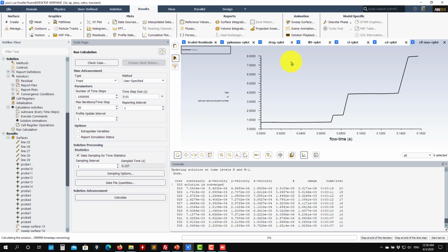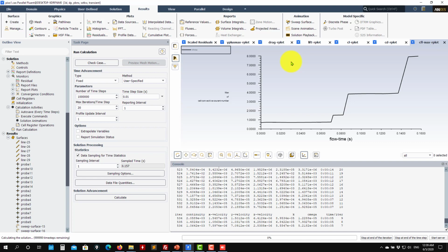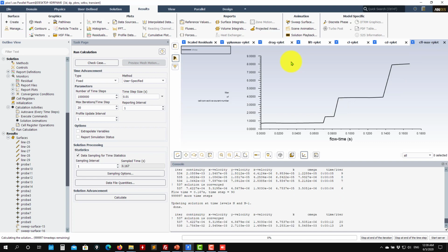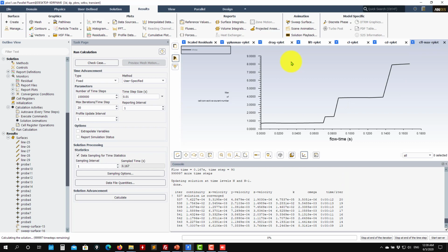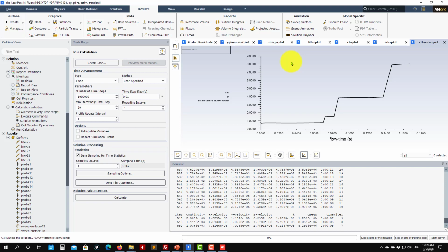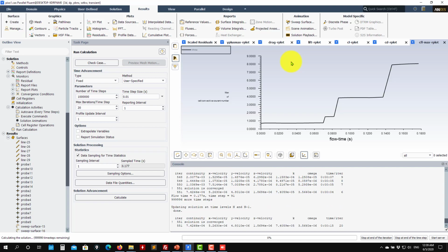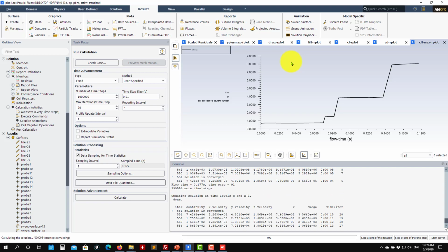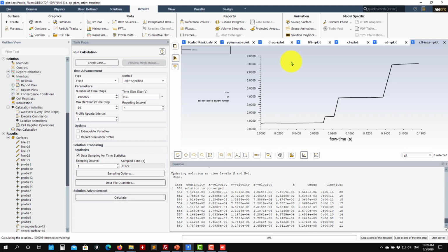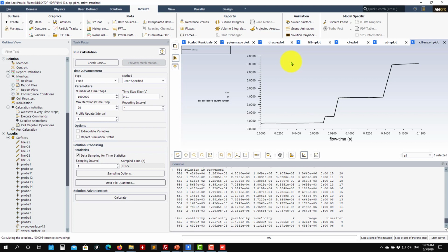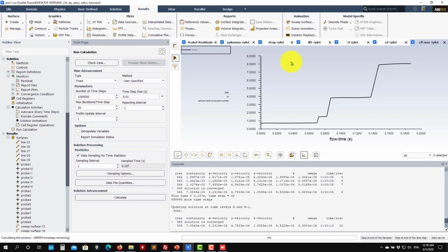So the theory tells that implicit methods are unconditionally stable. Okay, so meaning that you can use any CFL number and they will be stable. But the fact that you can use any CFL number doesn't mean that your solution will be good or that it won't diverge. Eventually, at very large times you will diverge because you're missing completely the physics. Okay, so all the time is a compromise.